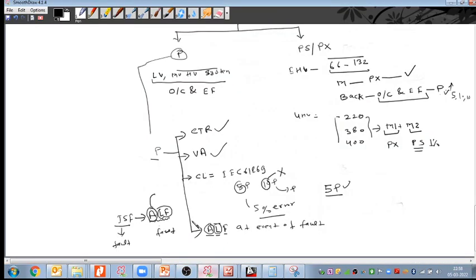Both parameters, the accuracy class and the ALF, have values 5, 10, 15, 20 and 30 available as per the IEC. As a conventional practice, instead of specifying them separately, we combine both parameters.